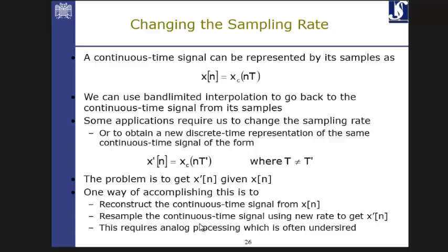So up and down sampling by themselves might have no meaning. They just look so crazy. But in practice, using subband coding and filter banks, you see that up and down sampling helps you have a highly efficient computational implementation of the filter banks.